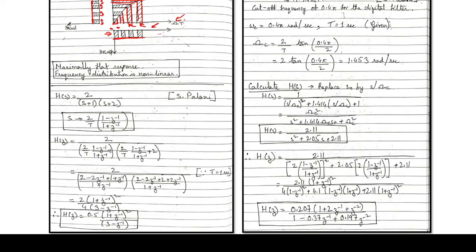When discussing the FIR filter, I had already discussed with you, if the frequency components are getting compressed within a particular zone, what happens? It becomes very difficult for us to design filters there, because the positioning of the poles and the zeros becomes very difficult. So due to that reason, the bilinear transform method is mainly used to design low pass filters, band pass filters or band reject filters which are working in the low frequency domains. Anywhere you have to pass the high frequency bands, under those circumstances this bilinear transformation method will not help you.